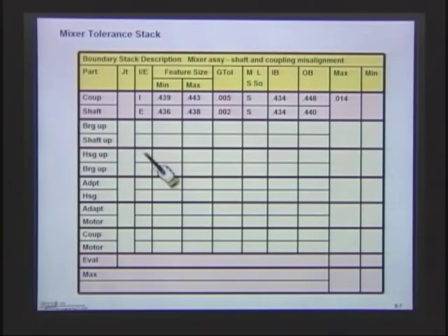So they're going to have joint number 1. This is going to be joint number 2, joint 3, joint 4, and joint 5. And after you did it, you're going to find out what the maximum is of each one. You're going to total them up for the max, and that's going to give you your maximum misalignment. And you're going to do the calculations down here in the evaluations and show me how you did them.